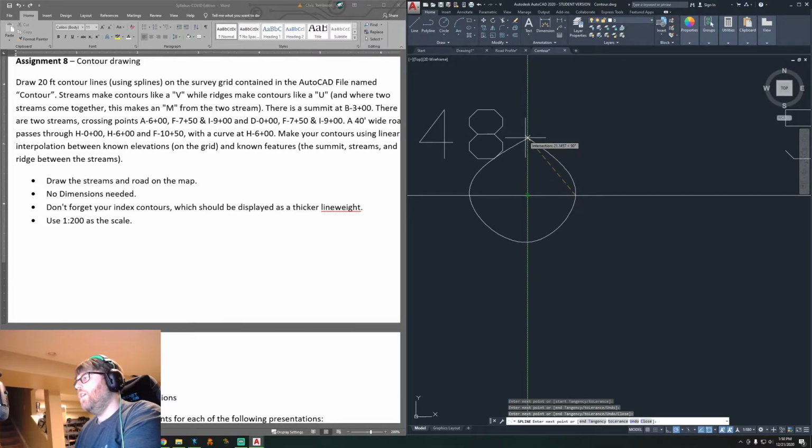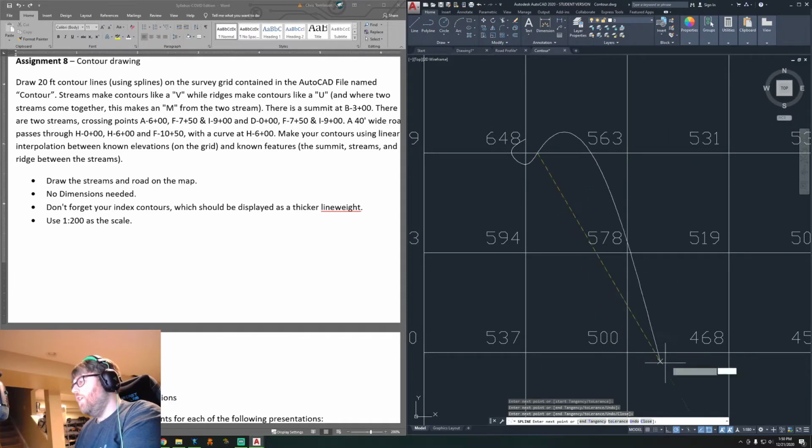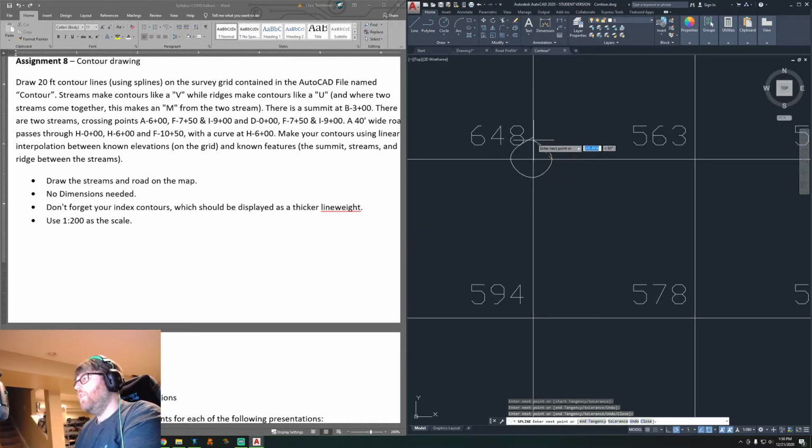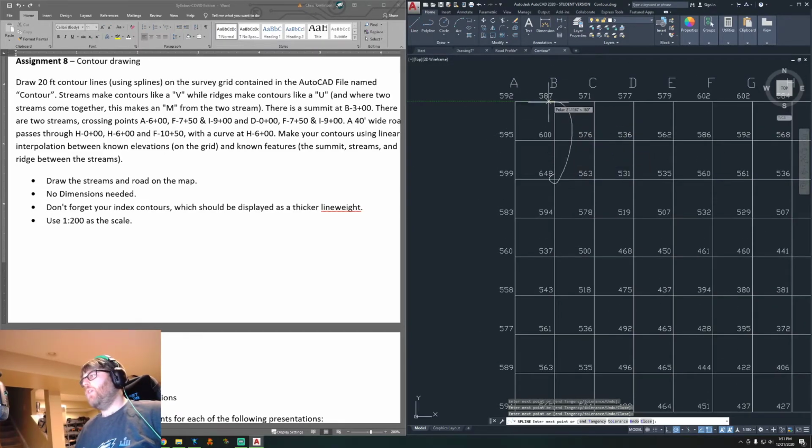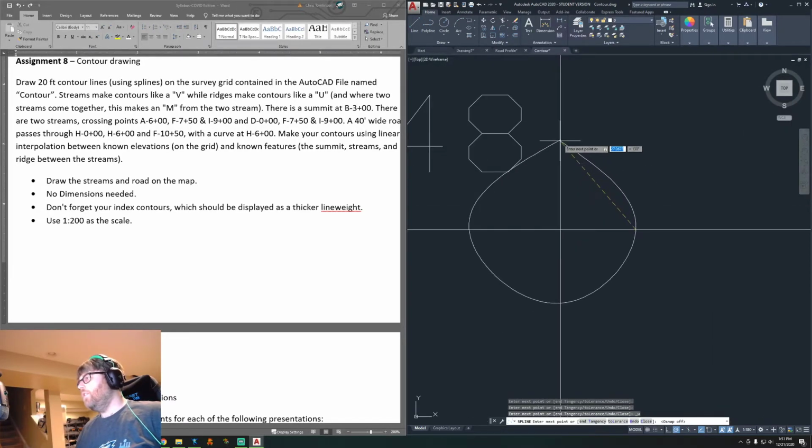If it wants to connect and not be a butt. So you're going to find in this assignment, sometimes it likes to be a little butt. Oh, I got it to go. No, I didn't. So this is actually a good learning point. Sometimes it snaps to a weird point. You could Control Z to come back to your last point, and what we may want to do is just turn off our object snap. So now I could just go to wherever I want and end it.